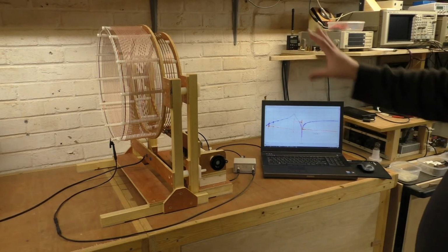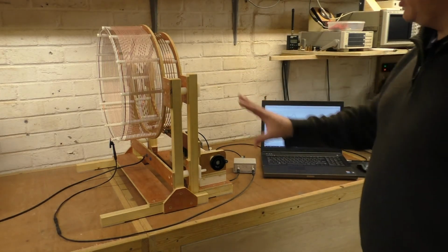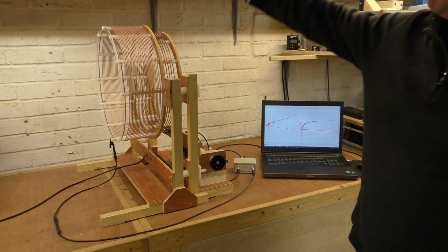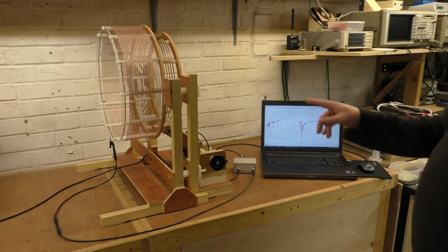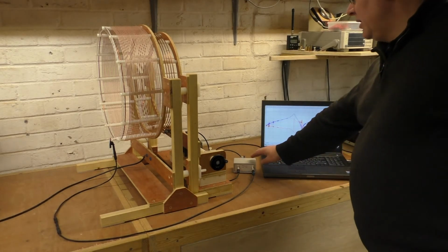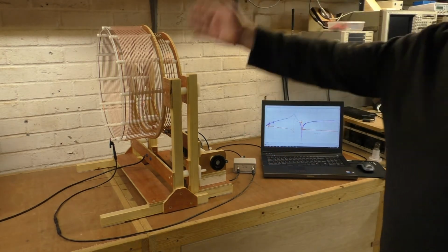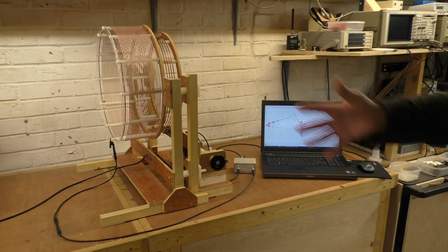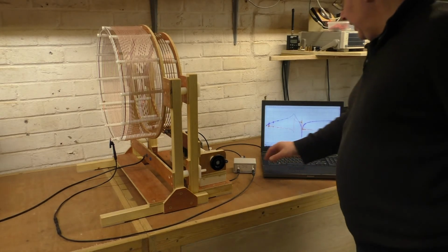We see the TC as one overall network. So the two-port network is the Tesla coil: everything from the input to the output, including the tuning capacitor, the primary coil, and the secondary coil. There will be some voltage magnification, and we need to make sure that there's not too much voltage magnification for the input. Of course, as the voltage is magnified, the current reduces in the secondary coil, so the overall power transferred across the system is less than unity.